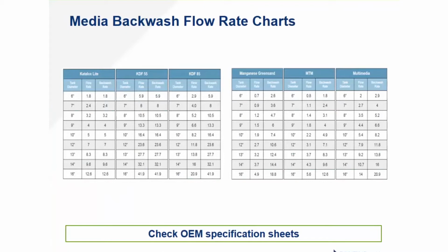And a lot of that is guesswork. You guys need to experiment and find out what works. So if you're seeing 13-inch tanks locking up with this media, you need to manipulate that backwash time, or lower your capacity, or increase the frequency at which you're backwashing, because that's just physically breaking up that stuff at the top of the tank.